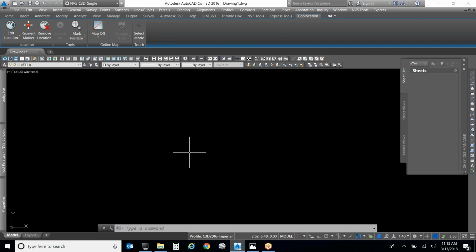and that utility is Pipe from Points. That is the preferred method here, right? In our typical projects these days, almost 95% of the utilities are probably potholed, right? So we want to hold off on creating pipes as long as possible, hopefully till we have that pothole information. If you create pipes not using that pothole information, you're basically going to have to delete them and start over when you have the pothole information, right? So make sure your project managers understand that process. And if they have any complaints, please send them my way, because it is a dramatic time saving. And also, you're better off if you do it once, not twice.